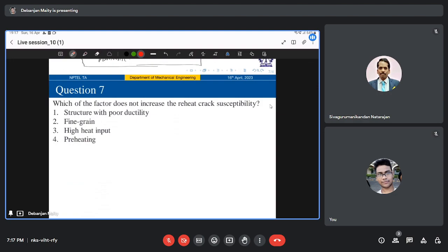So here, as I mentioned, reheat crack is a well recognized problem, of course, in some low alloy ferritic steel that contains chromium, molybdenum, or sometimes vanadium, tungsten to enhance corrosion resistance and elevated temperature strength. Now, this alloy steel is sometimes also called creep resistant ferritic steels and frequently used for elevated temperature service. These creep resistant ferritic steels are often reheated to about, say, 500 to 600 degrees C after welding to relieve residual stresses and hence reduce susceptibility to hydrogen cracking or stress corrosion cracking, right? However, cracking can occur in the heat affected zone during reheating, right?